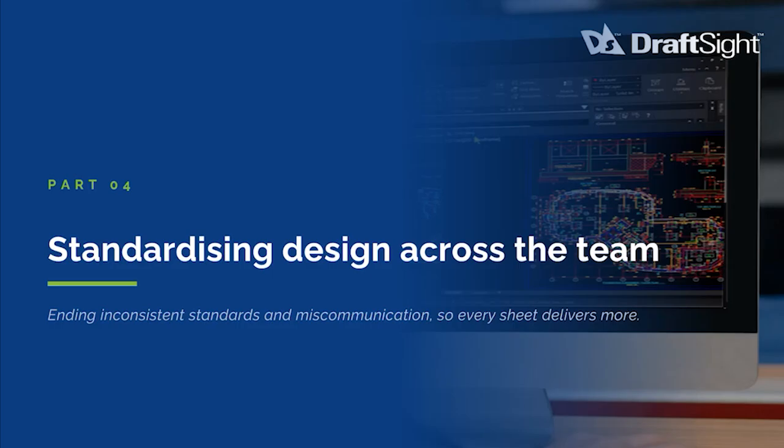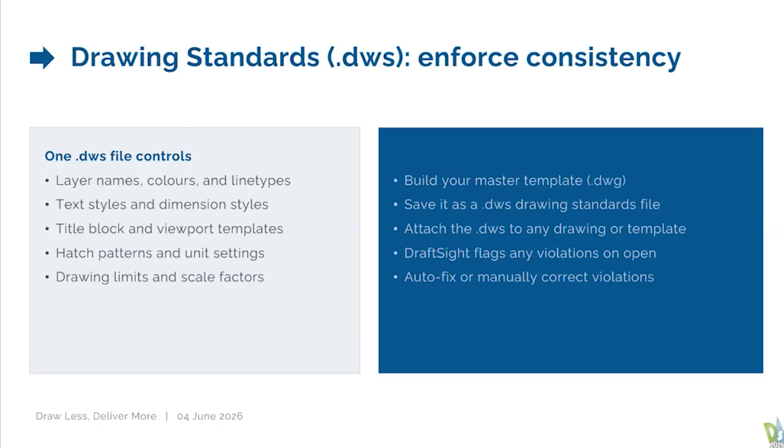So now we're looking at standardizing designs across the team. So, drawing standards. Again, most time gets lost because of inconsistency when it comes to users. Every user has their own way of doing things, and that does cost a project and the entire team loss of hours. So one, a drawing standard file control. The nice thing about this is you can have consistency in your layers, your colors, your line types, text styles, dimension styles, title blocks, and viewport templates, hatch patterns, unit settings, drawing limits, and scale factors.